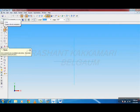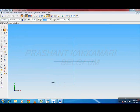To construct a hexagon base, what all things are required? I'll click somewhere else and give the side lengths. Base edge length is 25 mm. Enter. First line angle is 0. Enter. And the length of one of the sides is 25. Okay. Then the angle is 60. Then again the length is 25.